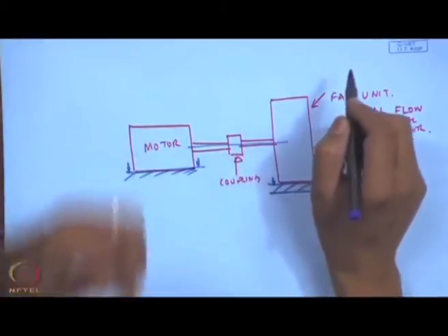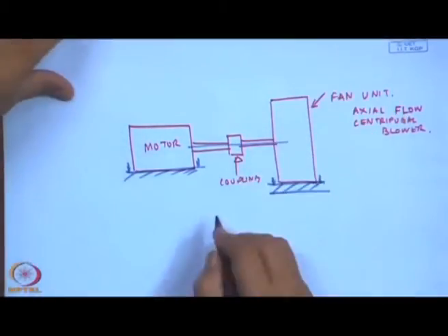They have very high power motors, and if these motors and the centrifugal blowers are not in perfect alignment, there will be a misalignment. So, all the problems associated with rotating machines which we have studied so far in terms of unbalance, looseness, misalignment, foundation bolt looseness, okay, they all manifest as vibrations.